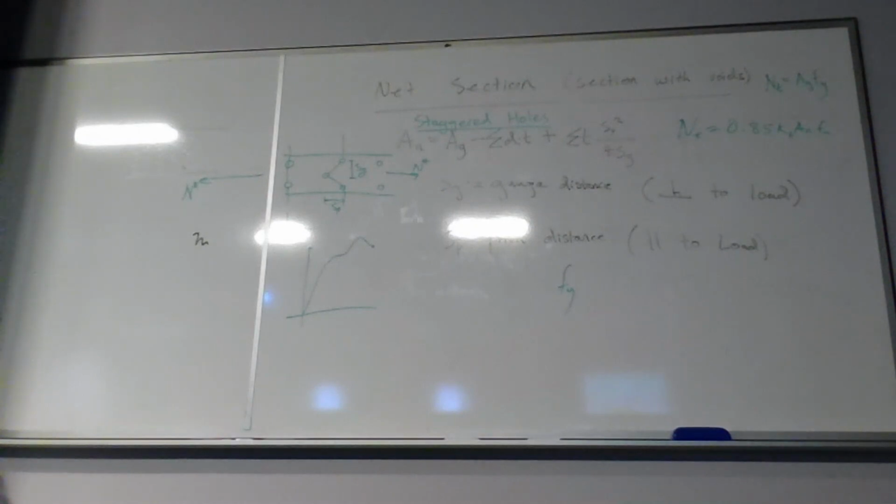Steel first yields and then snaps, so the strength to yielding is less, and if you kept stressing a bit more, then it'll snap. So the first failure mode, yielding of the gross section, is just looking at how much force it takes for your steel section to become bubblegum, and net section is looking at cracking specifically, and that's why we use it.